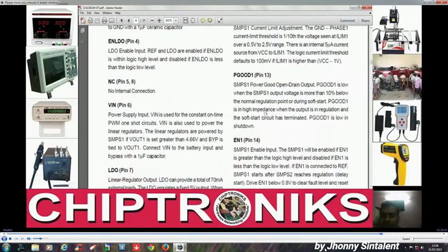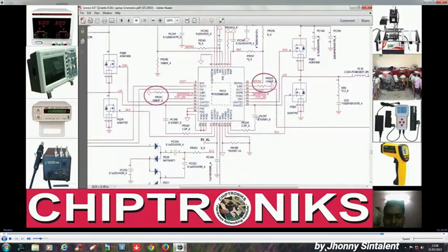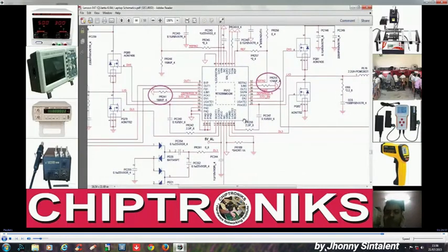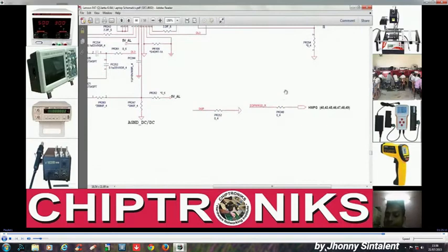And power good 1, all regulators supply power good, which are connected together to give feedback to the IO controller. We can see in the schematic, this will generate power good 1 and power good 2. So this is POK1, that is power OK1, and POK2, power OK2, and this power good will get converted to H power good, which is fed to IO, right?